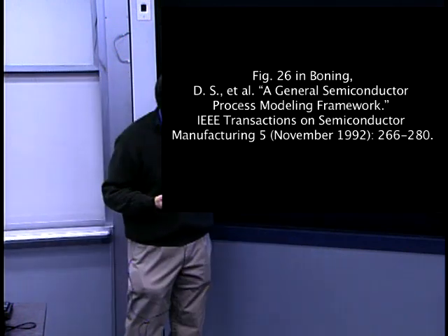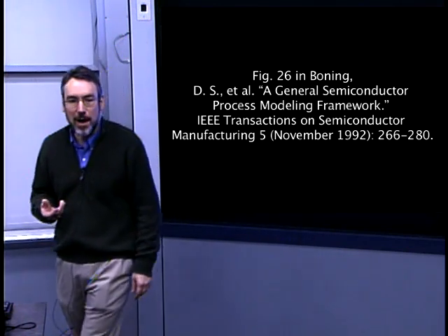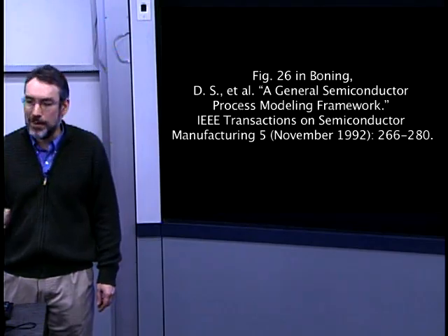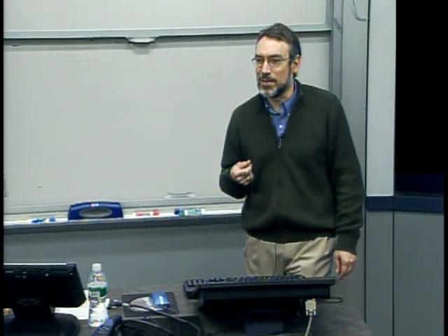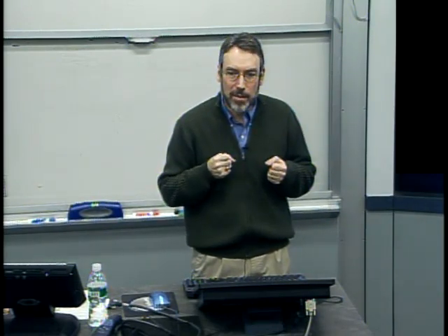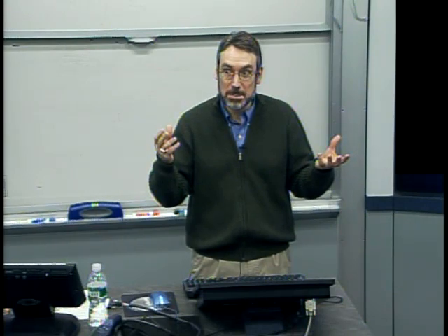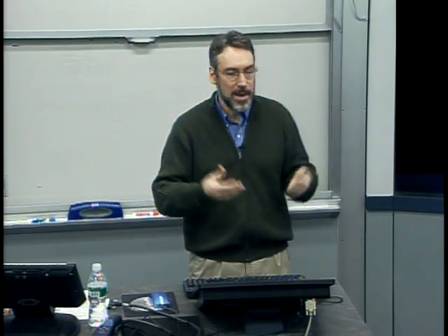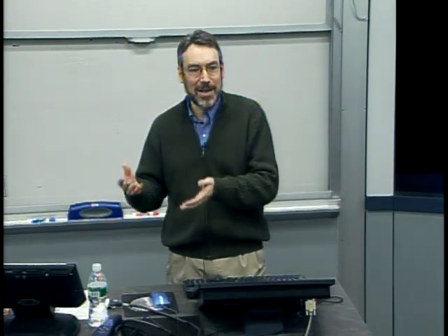But we also often have as side effects changes in the state of the equipment. And this turns out to be a big deal in much of semiconductor control. So for example, every one of those coating processes occurs in some kind of a chamber. I coat up a film, I coat aluminum on the surface of the wafer. What do you think happens to the rest of the chamber? It gets coated too. So over time, you will often get buildup of material in the rest of the equipment, and there will need to be other steps to go in and clean or reset the equipment state.